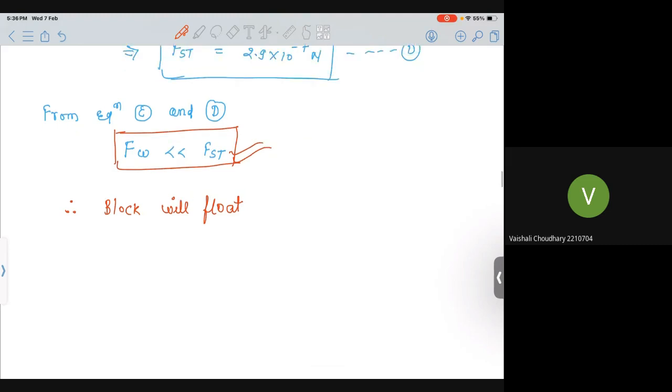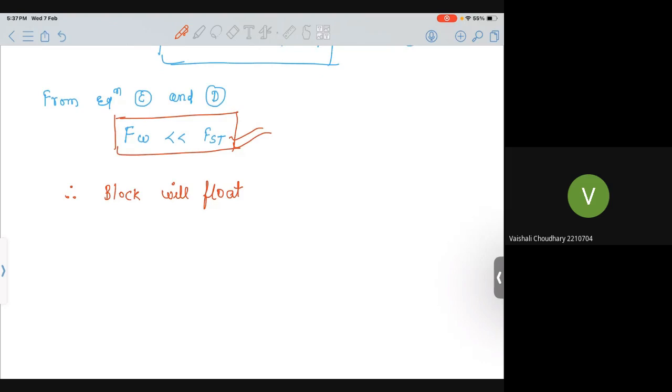Okay. Now we'll extend this problem and see what the critical length would be, because if we take a length of 1 meter, the downward force is the dominant one, but when we reduce the length to 1 micrometer, the surface tension force is the dominant one.